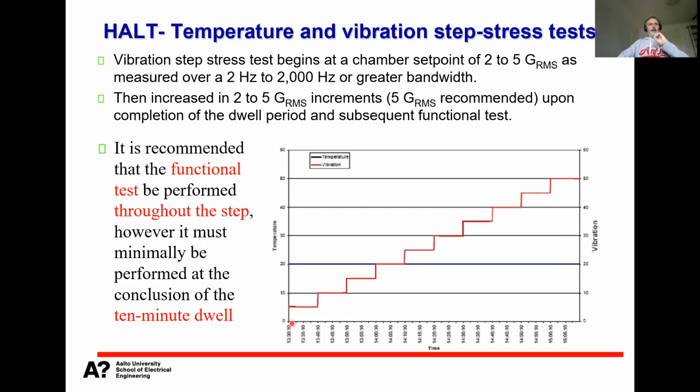It would be best if you could constantly monitor the functionality of the product during the whole sweep, but it might be that you cannot. Then you do the vibration sweep, and then you do the electrical testing. Okay, still working, then you jump to the next, and then you do the vibration sweep. So it depends. Basically, you can do the vibration sweep in a few minutes.